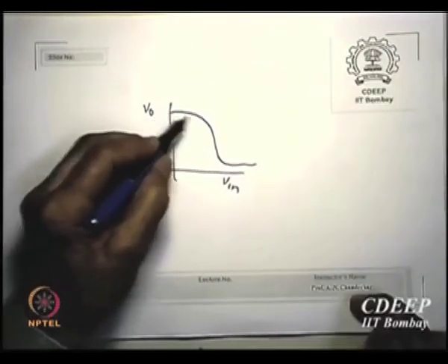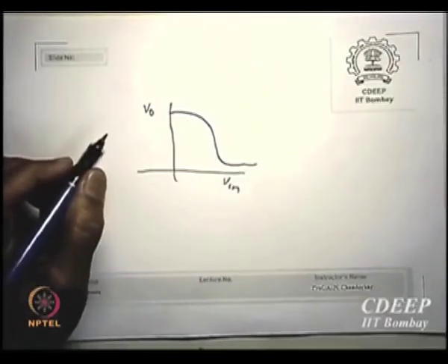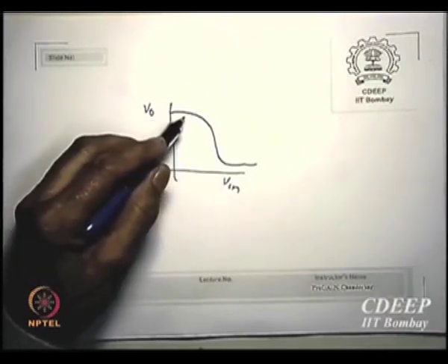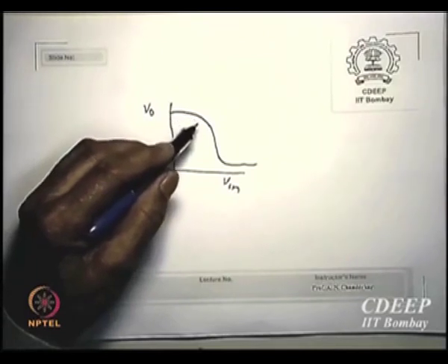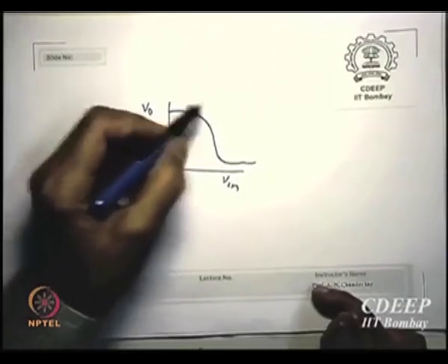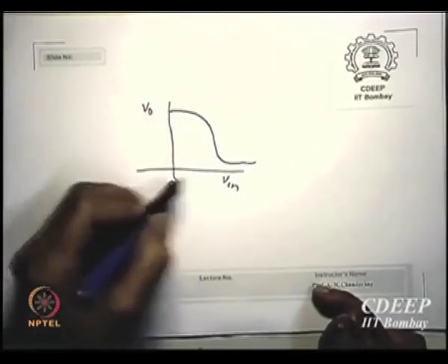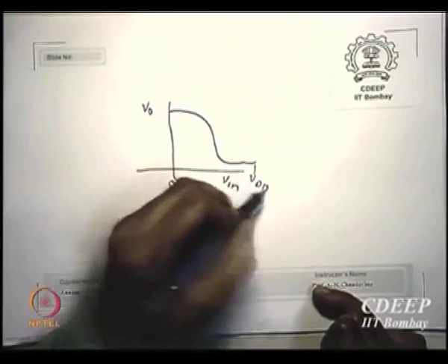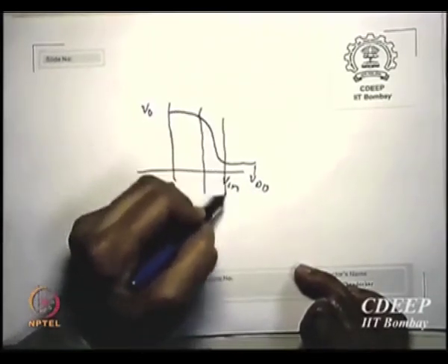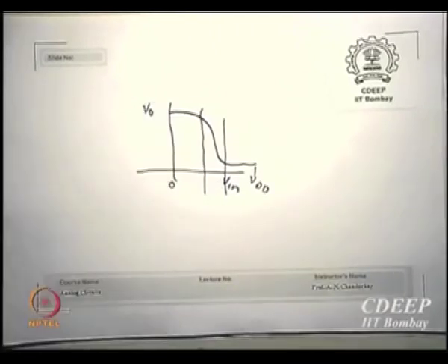You can see from here to here, Vout versus Vin is non-linear, because here one is in non-saturation and the other is in saturation; both in saturation, and the opposite happens here. In the case of digital, the signal goes from 0 to VDD, the input goes from 0 to VDD. Analog actually works only in this zone where Vout versus Vin is relatively linear. So you can see the available input range to me is how much?